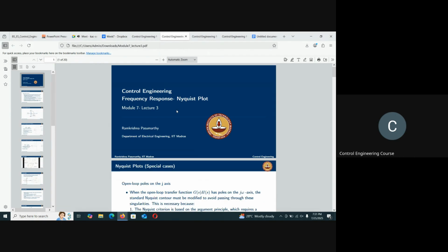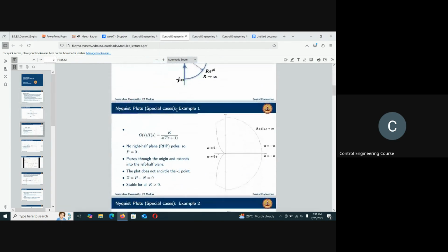Now we are showing special cases. Now take this. We got this part in the polar plot. Do you remember? Take the mirror image, and you complete the full Nyquist plot. And then you complete it clockwise, and you will get the full Nyquist plot around infinity. This point is invisible.